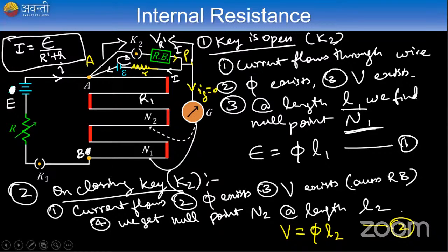So this is the point where I'm stressing, guys. Please note this. We have considered a small loop here. In this loop, the current remains the same when my galvanometer current is zero. Note that when my galvanometer current is zero, there exists a current inside this loop. Whatever amount of current enters this point, the same amount also goes back. Since my galvanometer current is zero, no current comes here. All the current which is coming from here is going back here.